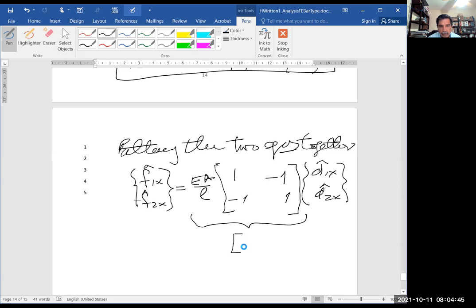This is what we call the stiffness matrix of one single element. And you see that this hat means that we are working in the local reference system. Okay, in the next session, we'll consider that we need to express this equilibrium in a global reference system. And in that case, we're going to take this hat out, but we have to do a transformation.